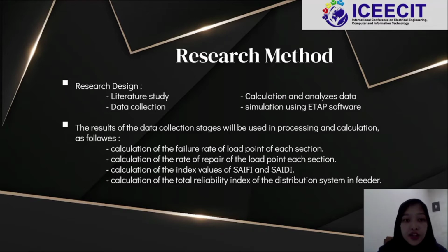The result of the data collection stage will be used in the processing and calculation as follows: calculation of the failure rate of the load point of each section, calculation of the rate of repair of the load point in each section, calculation of the index values of SAIFI and SAIDI, and then calculation of the total reliability index of the distribution system in the feeder.